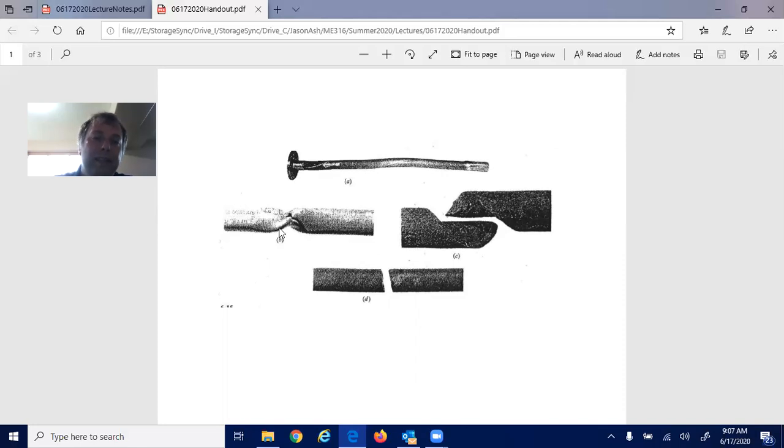On the other hand, engineers make use of this from a drive shaft perspective, where they design this as the weakest link so that the drive shaft fails before any damage occurs to your transmission or any of the other components. It's a lot easier to replace this than the transmission. So that is something that's often engineered into things, finding items that would be better if that failed as opposed to something else, so it's easier to replace.